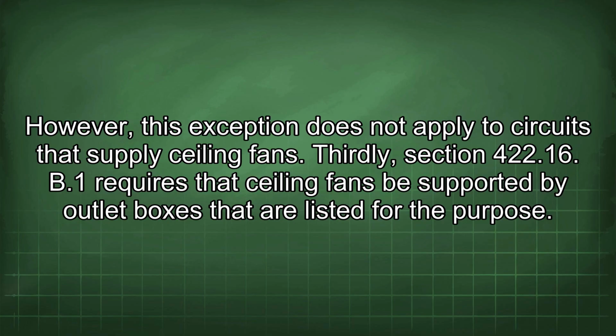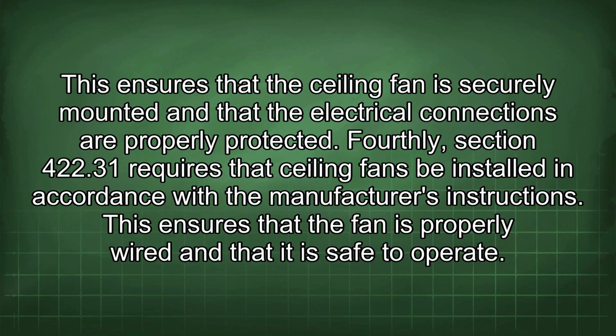Thirdly, Section 422.16(1) requires that ceiling fans be supported by outlet boxes that are listed for the purpose. This ensures that the ceiling fan is securely mounted and that the electrical connections are properly protected.